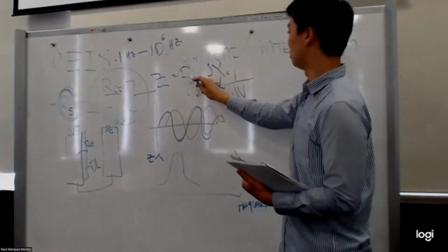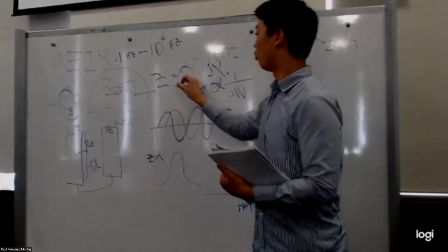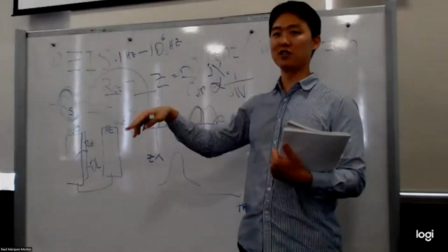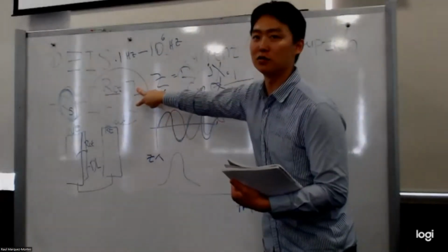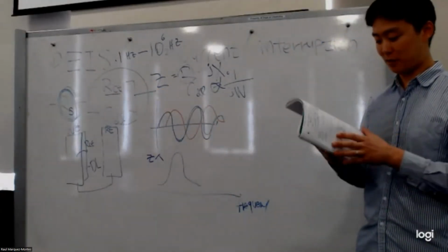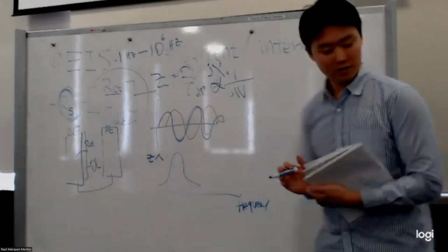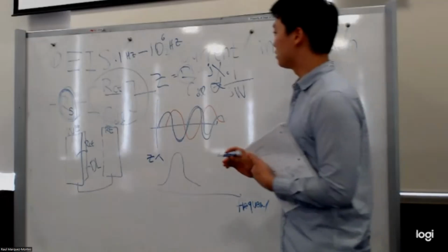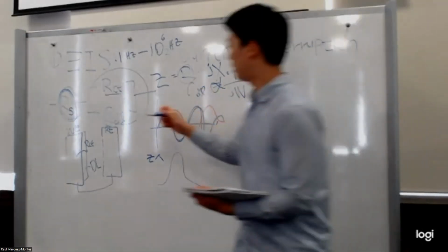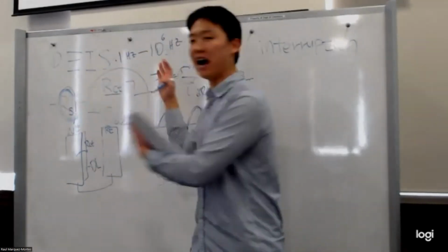The capacitor can contribute to both terms, and those two in parallel represent one impedance, and one impedance has its own frequency range. So these are coupled together. In short, using impedance analysis at a really high frequency range, we can decouple the solution resistance or uncompensated resistance from the other factors.